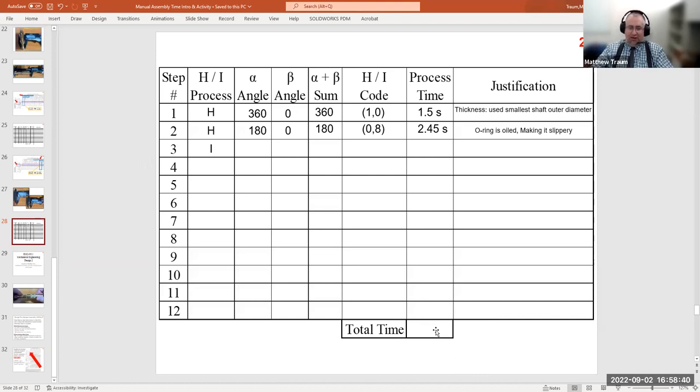And then that can be used, for example, to estimate the time to manufacture one product, and then multiply that over the number of products that you have to produce. And that gives you a total time to assemble all of the products needed to finish a particular order, which will then allow you to estimate the labor time and hence the labor cost. And that's how you can put the labor cost to do the assembly into the cost for that part that you give to your customer. So that's how that works.